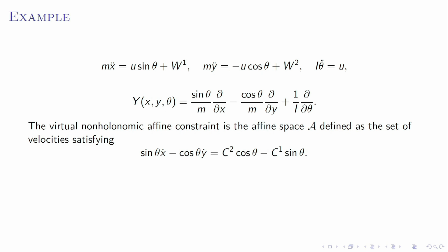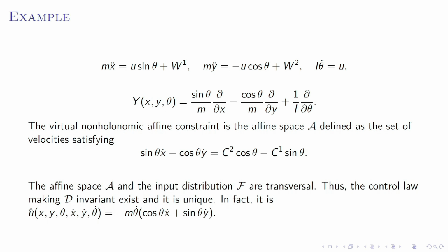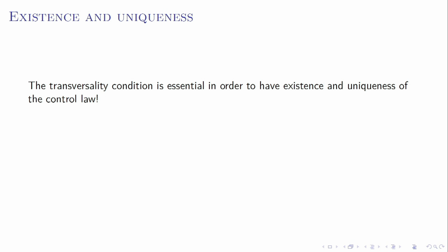Under these conditions, we wish to see if this affine constraint appearing here is control invariant. This constraint basically means that the only way the boat can move sideways is due to the effect of the current. We are not forcing the boat to move sideways. It turns out that in this situation the hypotheses of our theorem are met, and there exists a control law, which is very easy to compute, and the constraints are satisfied by our system.